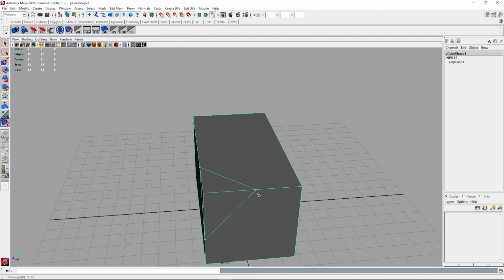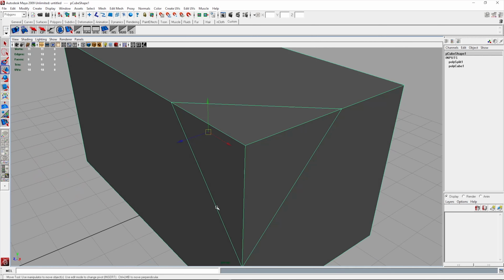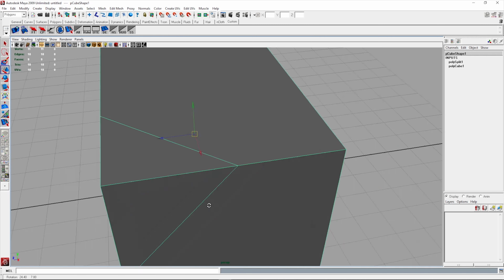Now it's not snapping in, you can see. So if I go like that, you can see that those 2 points do not align. So while not touching anything on the keyboard, we're going to hit W to get out of the tool, or hit Enter to execute that tool. See, it's snapped to that edge. Because it knows that you want it close, and it's gone, okay, they're the 2 closest vertex points, and it's going to snap them together and close that loop.